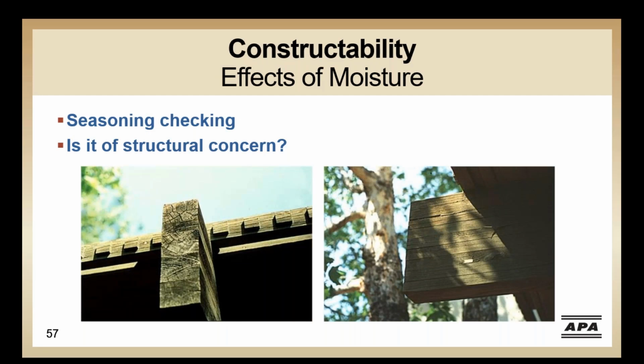Whether they are treated or not, checking of beams can occur. The question is, is it a structural concern? APA provides guidance in reviewing checks in glulam. Checks in other structural composite lumber products should be reviewed with the manufacturer.